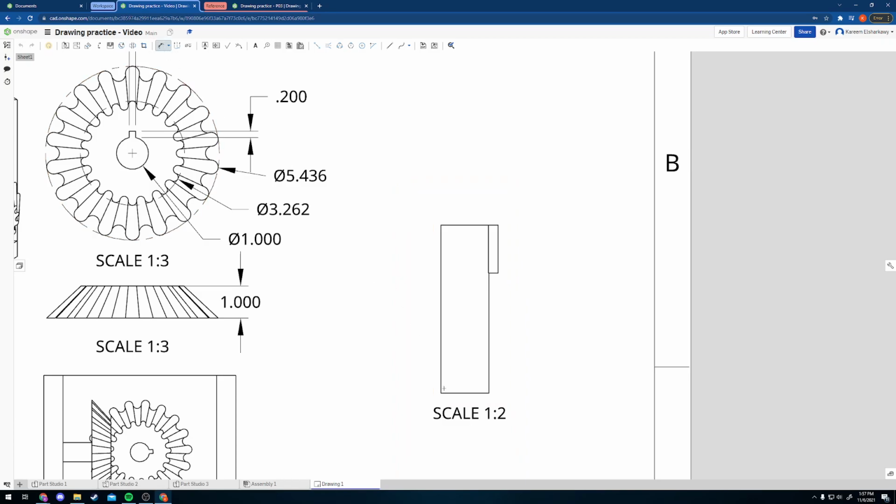So instead, you could either choose this bottom edge, or you could just choose these 2 lines, and it'll show the proper 1 inch. Yeah, even though I've done CAD for quite a while, it's very easy to make those kind of mistakes. It's just understanding why it's doing that. And you can always move this around to make it a little cleaner. And then I'm going to go back to our dimension tool.